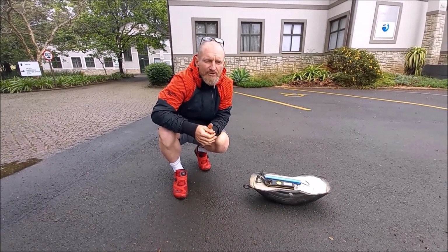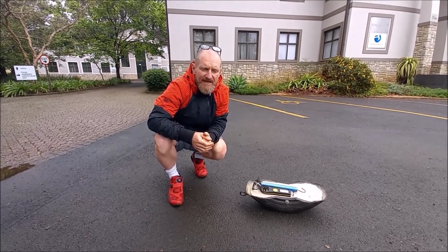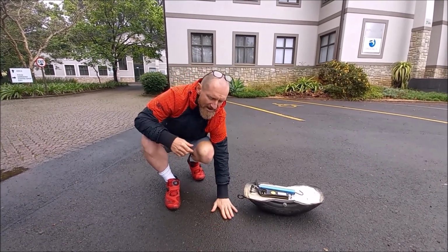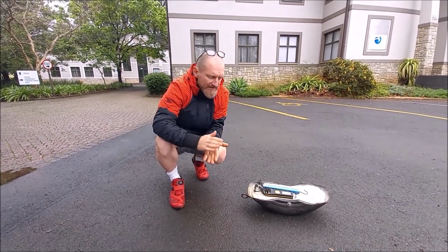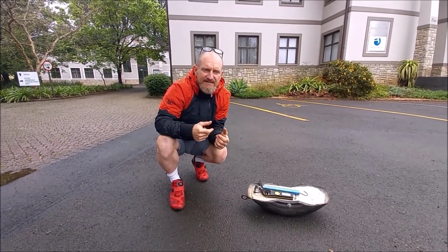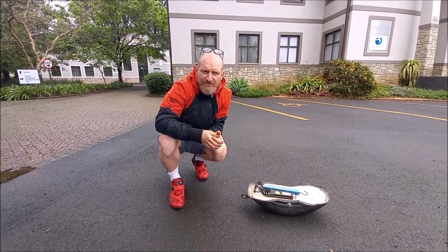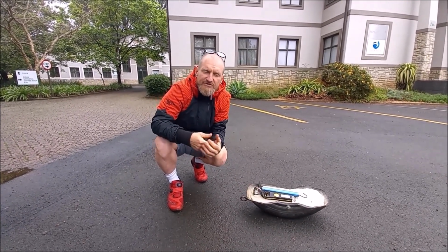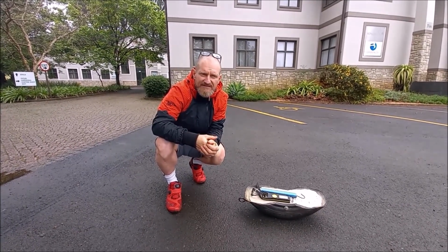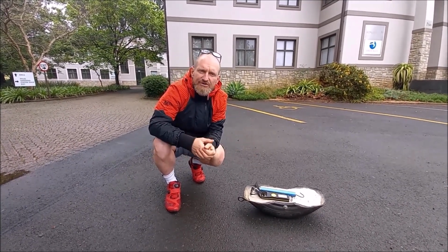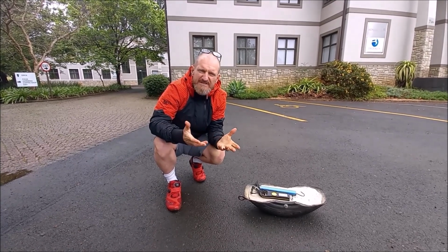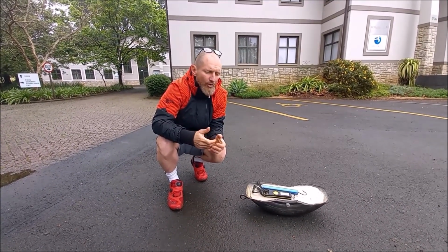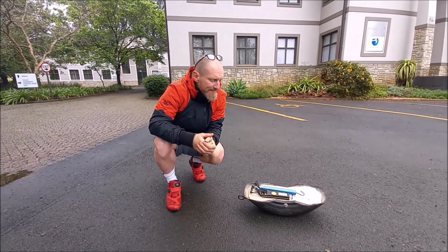Okay, so one of the most important things we do in any crash investigation is literally measure, in what's known in layman's terms as, how rough is this surface. The relevance of that is that in any application of any calculation, you would need to know how rough the surface is. So you would typically appoint a factor for a good condition road of 0.7, 0.5, 0.8 mu, which is your coefficient of friction reading.